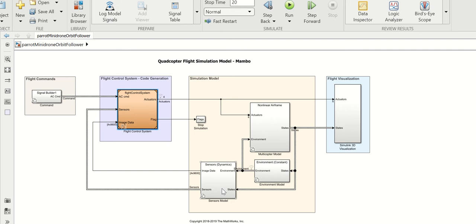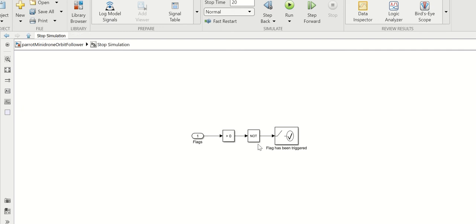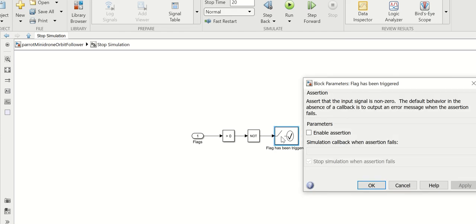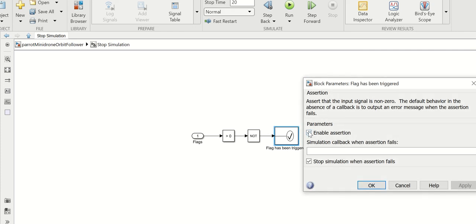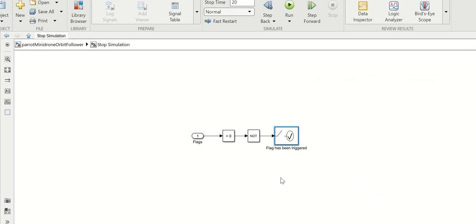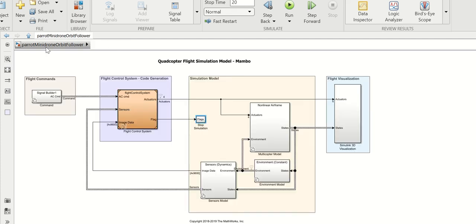Now there's some things you might want to watch. Sometimes if you click on this little box here, this is the one that stops the simulation if it crashes. Sometimes it's better to switch this one off by clicking on this. You can enable it or disable it. If you click on there, it enables, which is how it is at the start. If you click on there and disable, then that's a good little trick to keep the thing going.